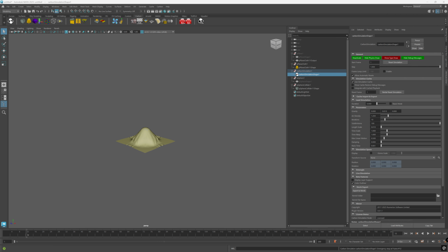I'm going to put this aside now, and tenfold increase the panic time, and I would expect it not to trigger anymore. And here we go, our simulation seems to run through fine, we got no problems, but our panic time is still there. So if any of the frames now takes about 10 times as long as it would normally, then panic time will trigger. And this is how you would tune your safety feature.